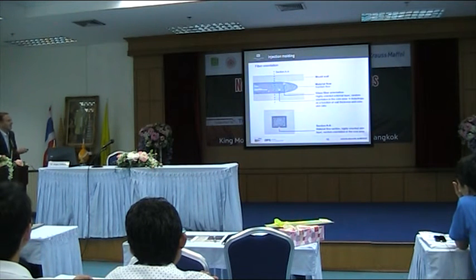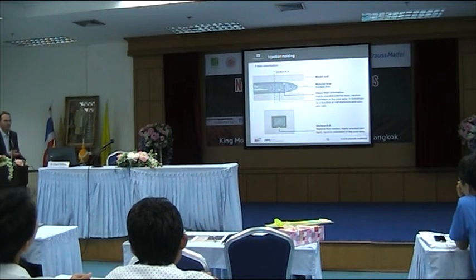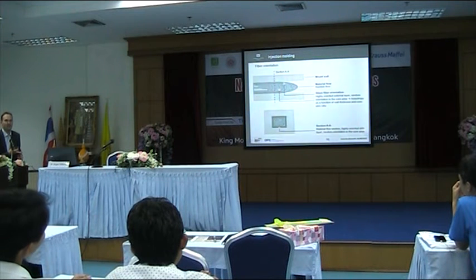The thickness of the layer depends on the injection velocity and the viscosity of the material and so on, but you always have this orientation in the part. So the fiber length reduction is given, and the fiber orientation you cannot influence so much. Okay?